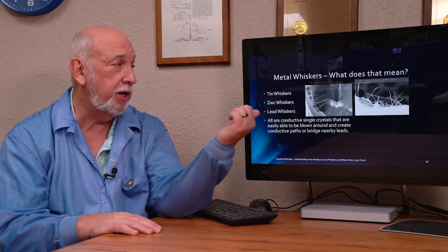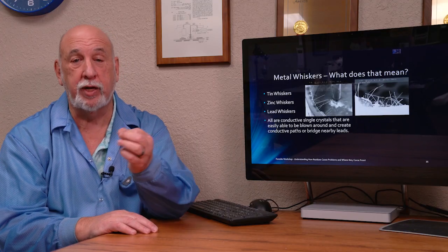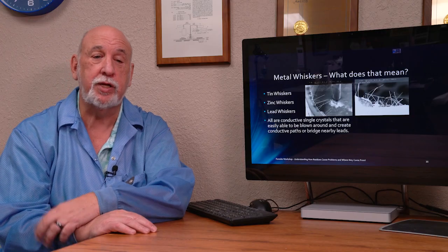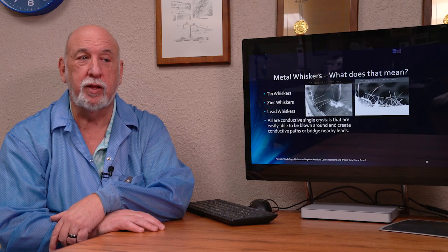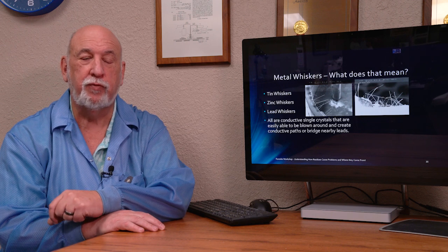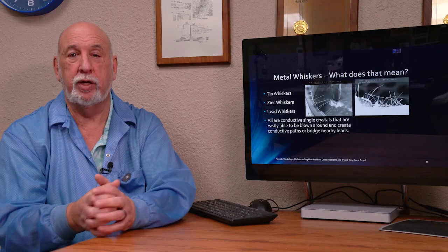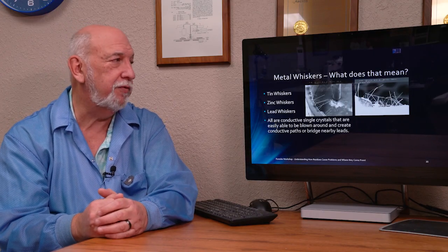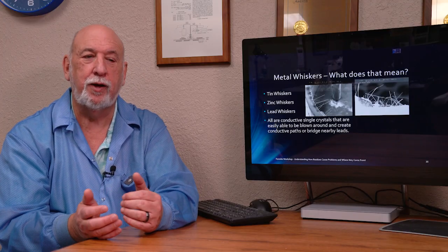We've seen a number of metal whiskers inside of some of the camera connector mounts. We've seen a lot of structure where the metal whiskers form in the solder joint and grow out of the solder joint on a lead-free alloy. So we have a number of things that contamination feeds to.